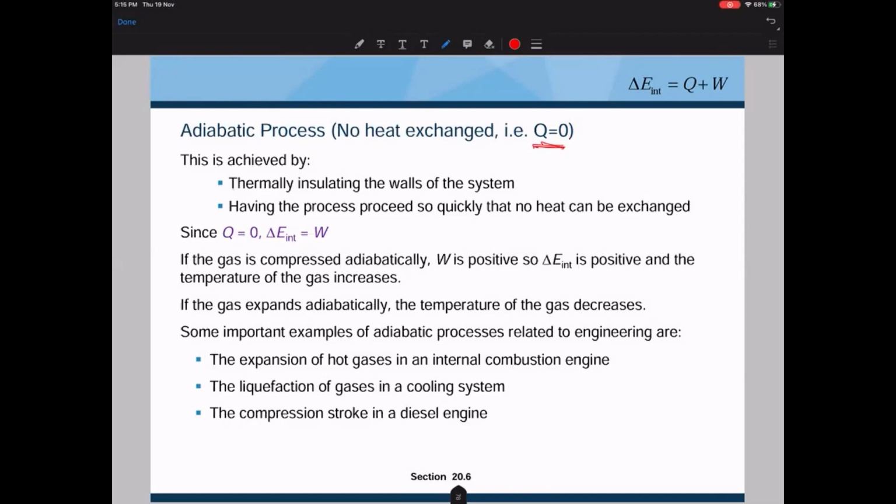So at the end, what you notice is that the surface of the can becomes very cold because the heat energy takes time to move to the inside. So in that case, you could regard the process to be adiabatic. Not 100% guaranteed, but it is quite close to Q equals 0 if the time is short. Okay. So when the gas is undergoing an adiabatic process, Q is equal to 0.